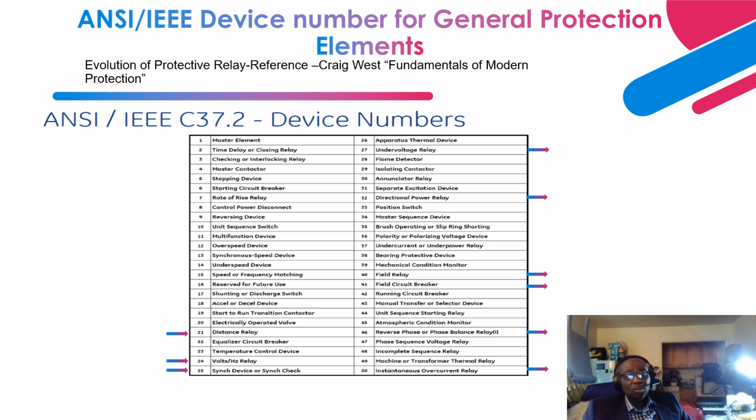So let's say a negative sequence unbalance of 5%, 6%, 10%, for a certain period. So I squared T, and it also provides a K, and the K number is a multiplier provided by the manufacturer.